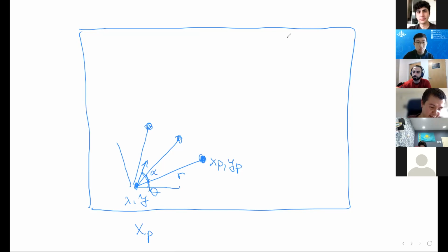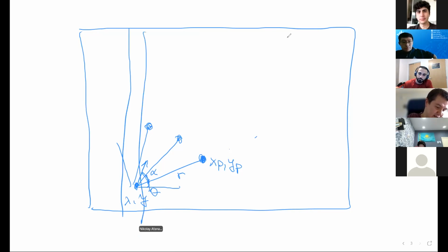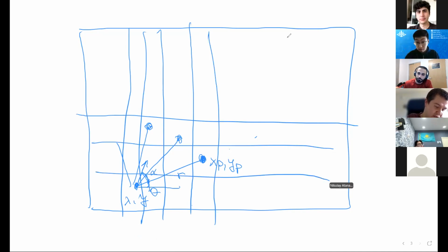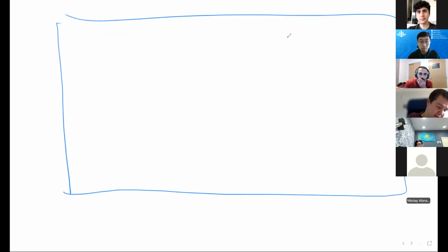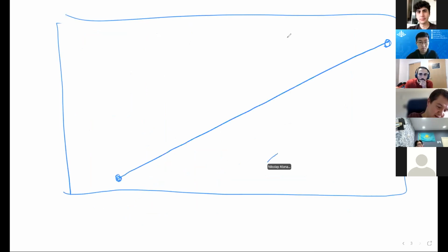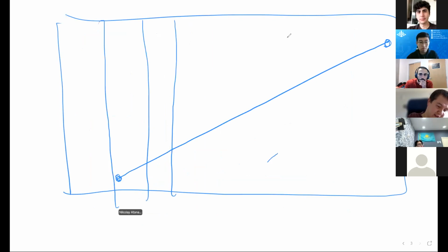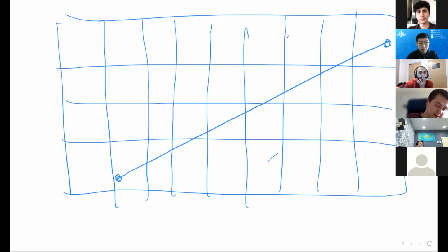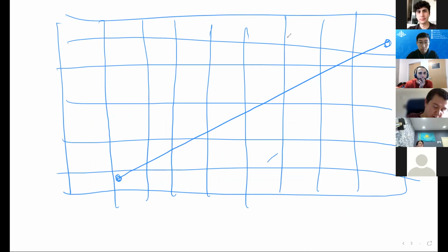In the second demo, what we're doing is slightly different. We said we're going to place this grid on the map. Let me simplify this drawing a bit. Let's say this is our robot. We have a ray, so this is the LiDAR ray, and then we have this grid for the map. Then we're going to check for every box whether this line goes through the box or not, and we're going to keep some sort of confidence level for each box, whether it's free or occupied.